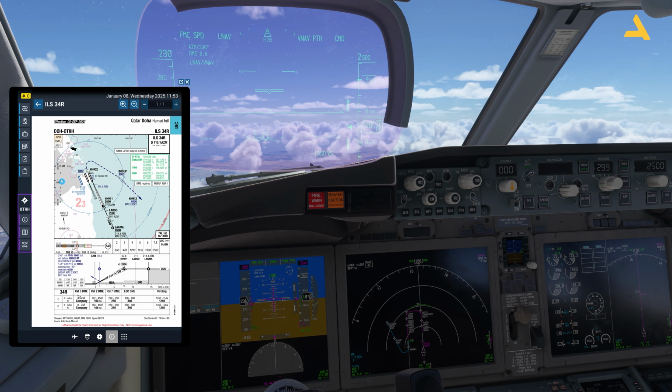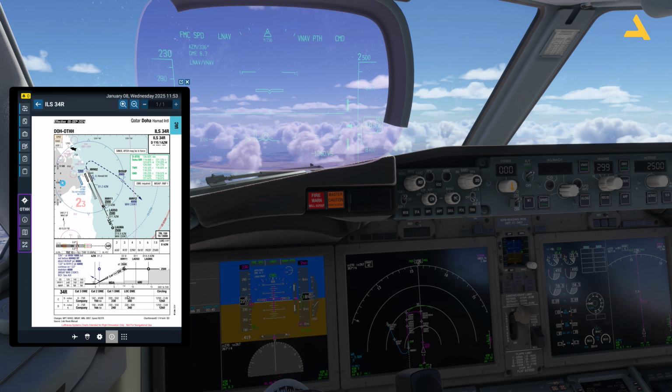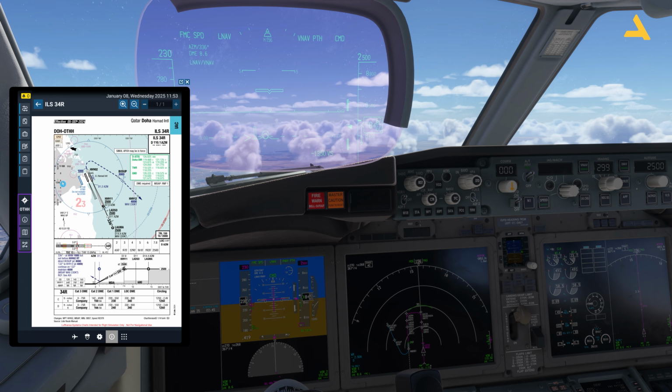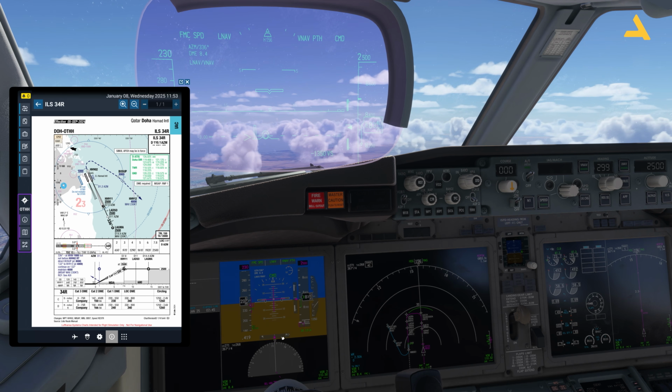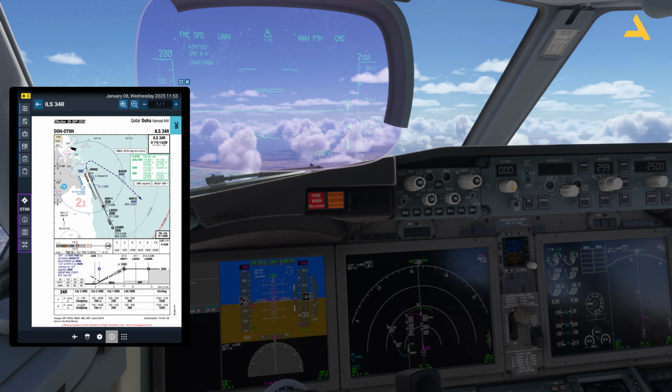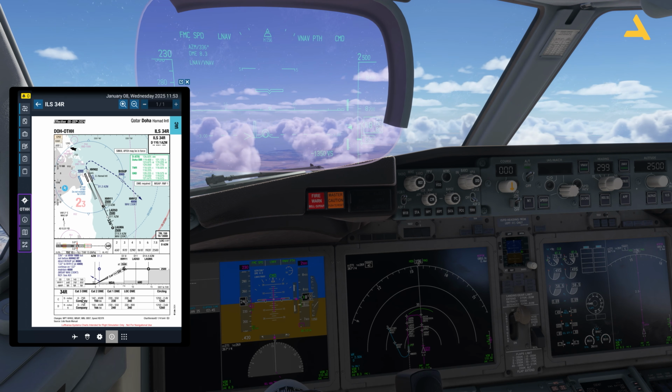Category 3 is the most precise ILS approach and landing. And then you have Category 2, Category 1, and localizer, DME, which is the least precise ILS approach and landing. So as ILS is carried out by the instruments, that's fine. It has to be accurate. This plane can perform a Category 3 landing. So you can set the decision height to be 75 feet above the ground. The runway elevation is 13.